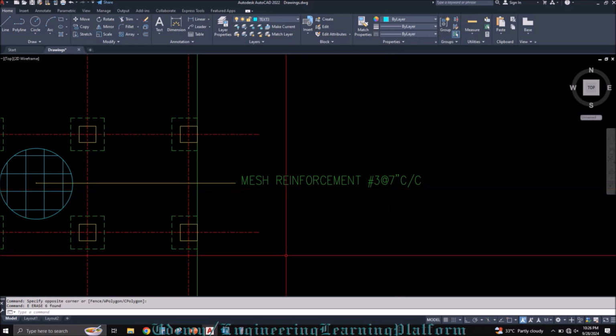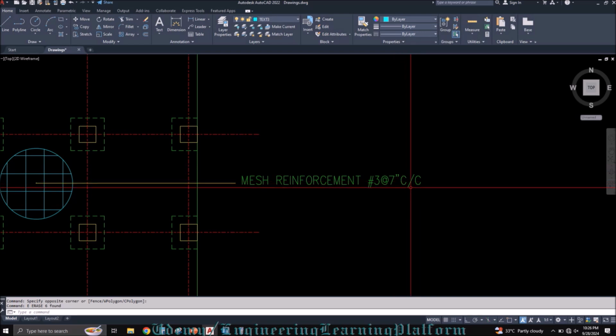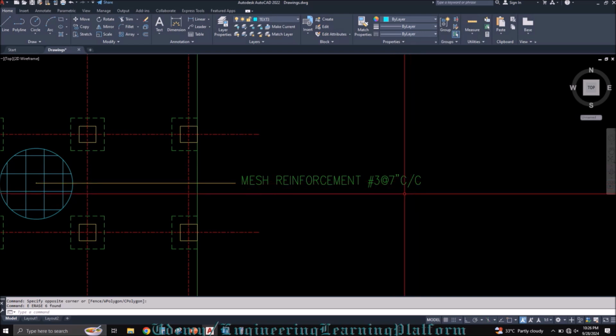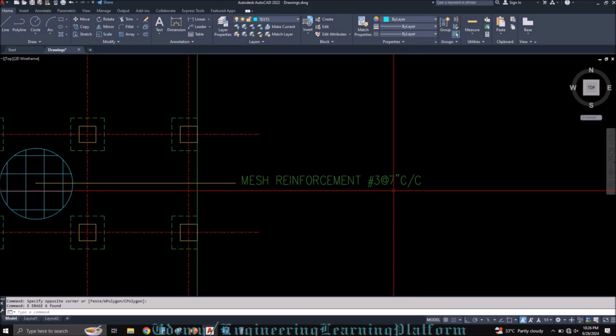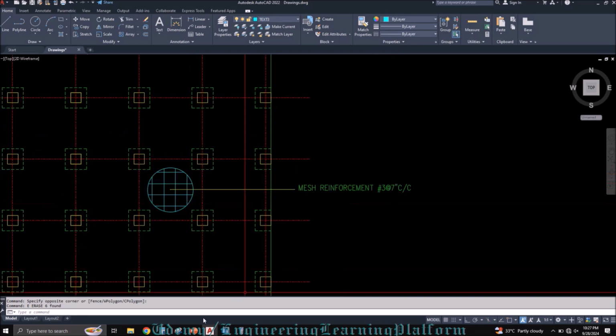So that's why we are providing 7 inches rather than 7.5 inches, because if we provided 7.5 inches and the extra reinforcement also number 3 at 7.5 inches, the actual spacing between the bars plus the extra bars would be 3.25 inches, and a quarter inch is not an easy thing to measure on site when providing the reinforcement spacing.